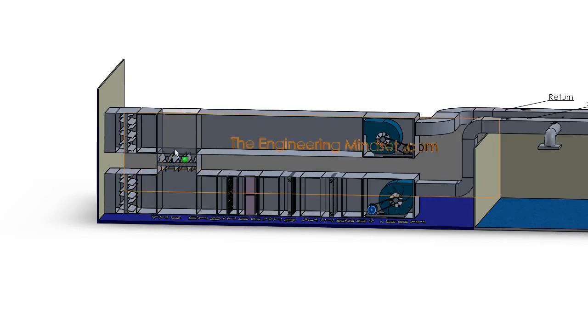The BMS has decided how much air can be reused and recirculated. You could also put this on a manual system and change it seasonally if you don't have a BMS, or if the BMS for some reason isn't working, but obviously the more you can automate, the better the controls will be. That will then bring that in, and then you need to filter that.